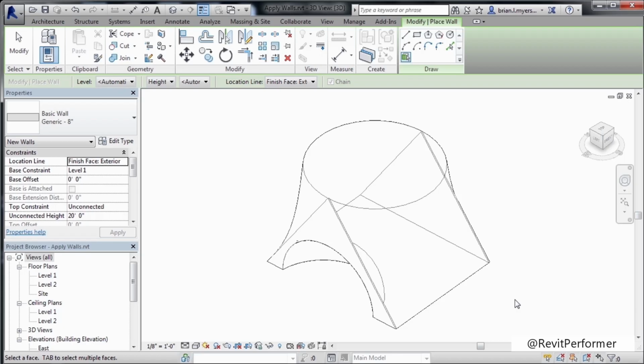We activate that command and then draw in the areas where we would like to see our floors or our roofs located. So far we have 3 different walls associated with this mass object, but we also want to place on the 2 sides some curtain walls. Now unfortunately, if you just select the wall command and go to curtain wall, it'll fail. What we need to use is a separate command to apply the curtain walls to this shape.